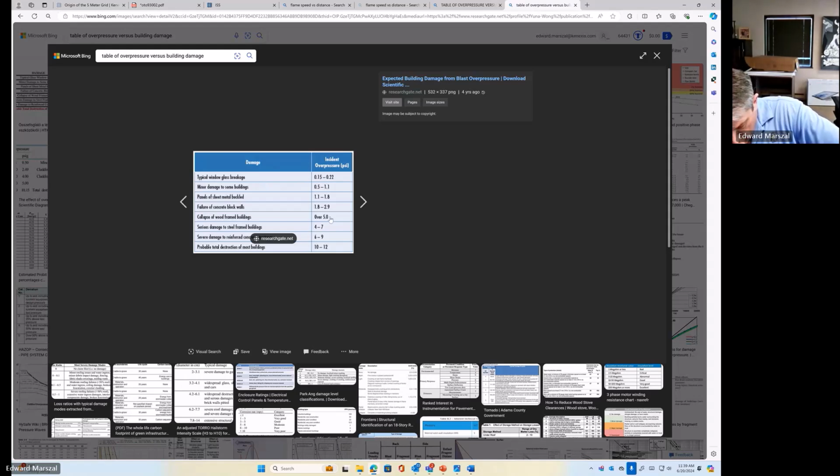We're not talking about a massive amount of gas, as an excursion. We're talking about a vapor that is going to be accumulated over time and creating a flammable atmosphere. So are we talking about maybe a line of sight or a combination in between line of sight and point detection? Okay. It all depends, and again, I'm speaking in generalities here.